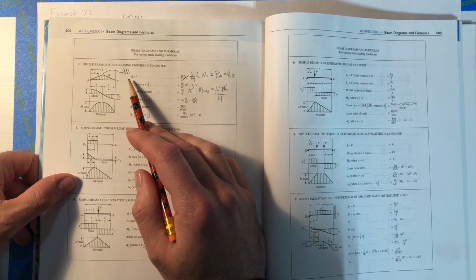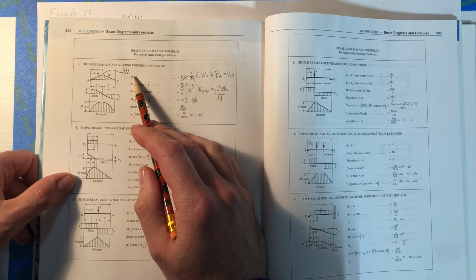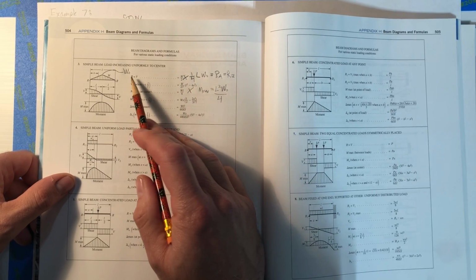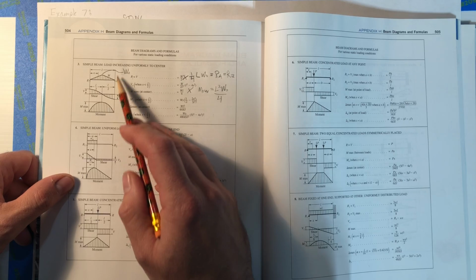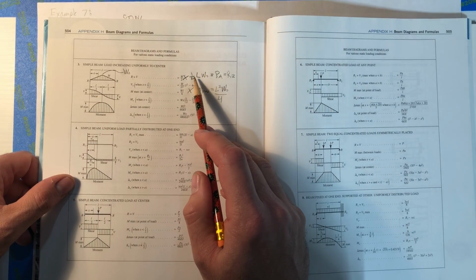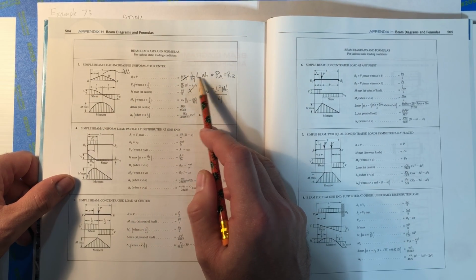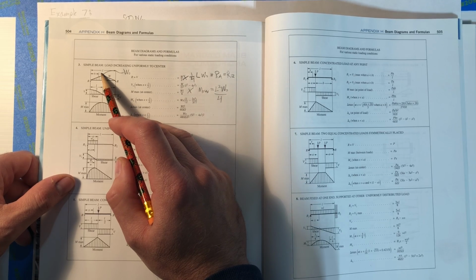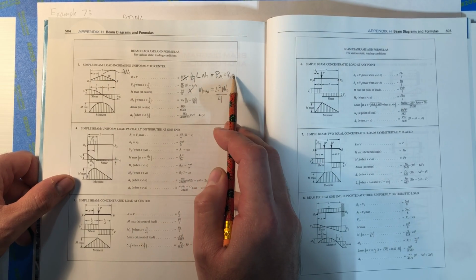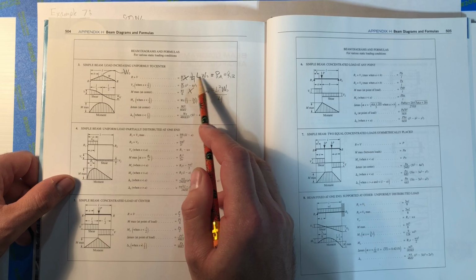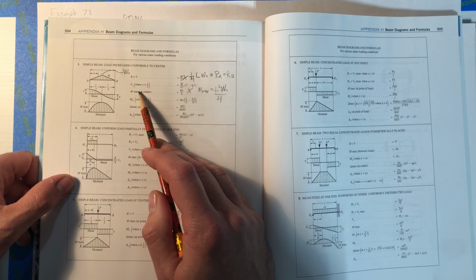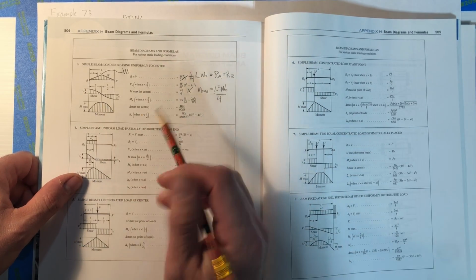So if you can, in your book, change this first one from R equals V, cross that out, and put R or V, the reactions, or the shear at the ends, is equal to 1/4 the length times the peak value, W0. And that's equal to the reactions A and reaction B. So 1/4 L W0.